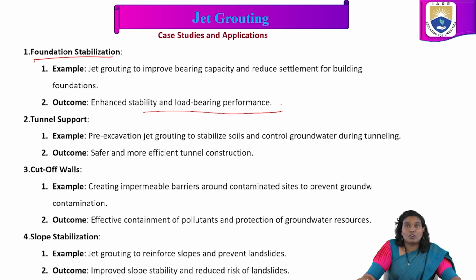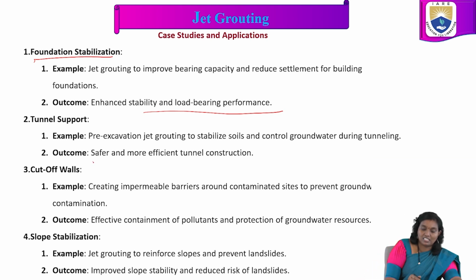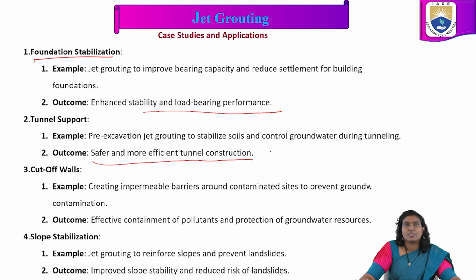In tunnel support, pre-excavation jet grouting is used to stabilize soils and control groundwater during tunneling. We use a suitable jet grouting technique, whether single fluid system, double fluid system or triple fluid system, based on understanding the soil properties. The final outcome is safer and more efficient tunnel construction using this jet grouting technique.